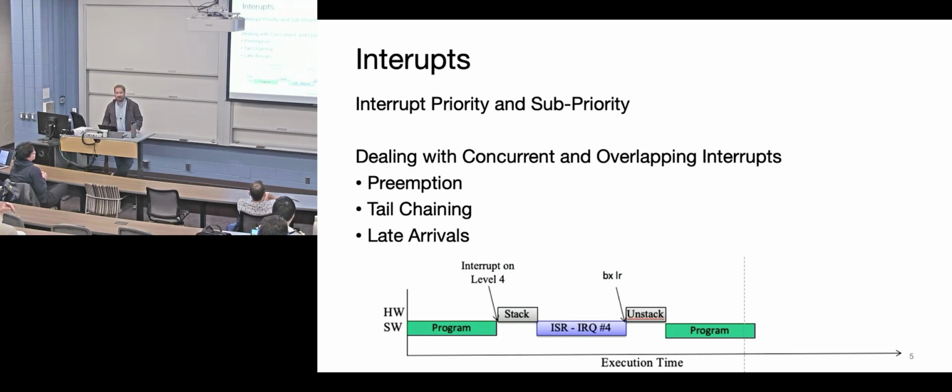We can always pull up those slides if people have more questions or specific questions. Yep. For late arrivals, for the interrupt that interrupts during stacking, the one that we were initially going to go into, that gets set to pending. Yep. It's not run yet. It never became active.